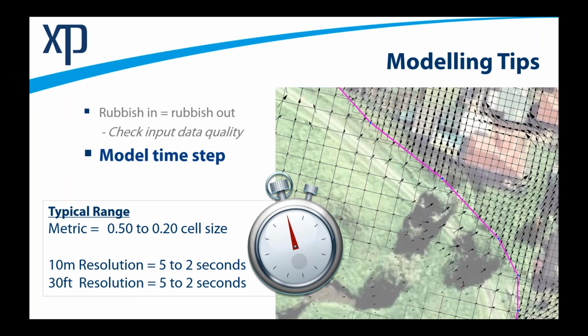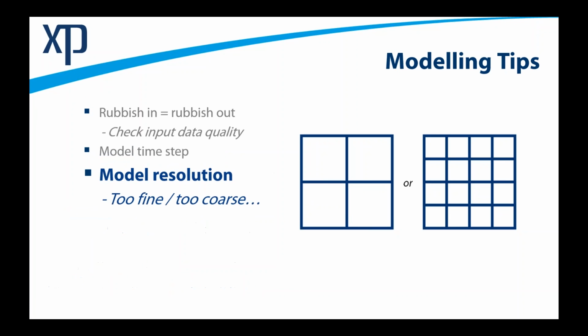Okay, so let's look at model resolution. This actually ties in with the time step a little bit. What should you use? As a starting point, I recommend just put some thought into considering what you're trying to model. Make sure that your model adequately represents the key topographic features.